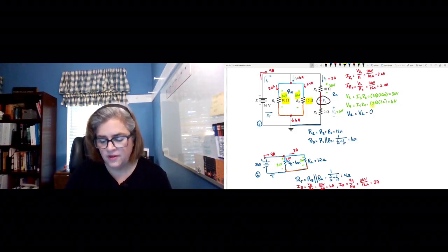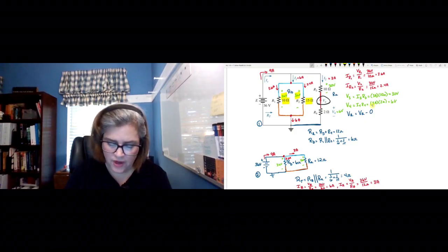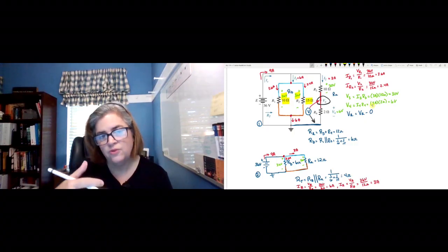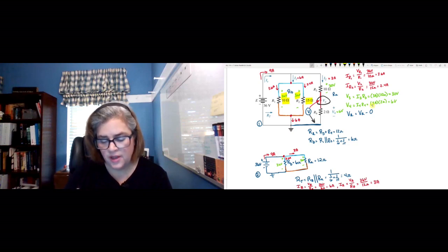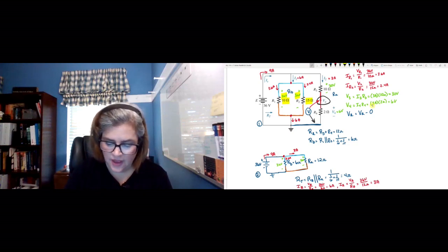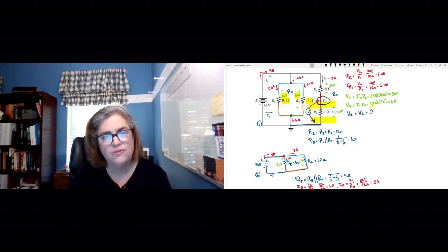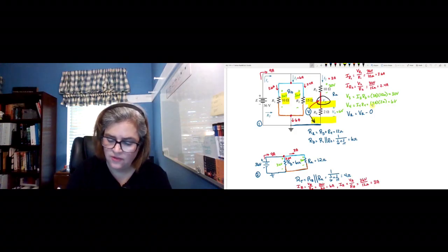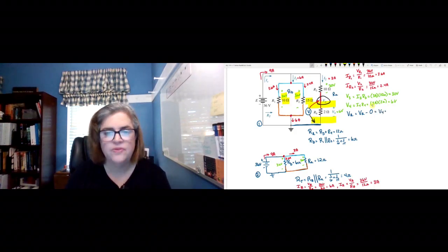So what that really means is if I put a voltmeter right here and I put the red lead pointing there, the black lead at ground, what would be the difference in voltage from that point to that point? Well, notice that that's actually in parallel with my R4. So VA in this case would simply be the same thing as V4, which would be 6 volts.